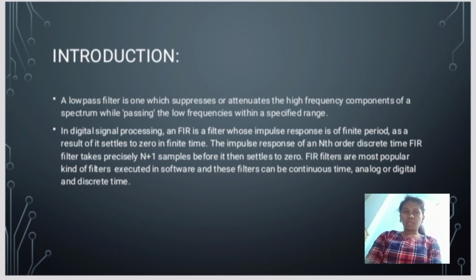So here is the introduction about the low pass filter. A low pass filter is one which suppresses the high frequency components of a spectrum while passing the low frequencies within a specified range. In digital signal processing, an FIR is a filter whose impulse response is of finite period. As a result, it settles to zero in finite time. The impulse response of an nth order discrete time FIR filter takes precisely n plus 1 samples before it then settles to zero. FIR filters are the most popular kind of filters executed in software.